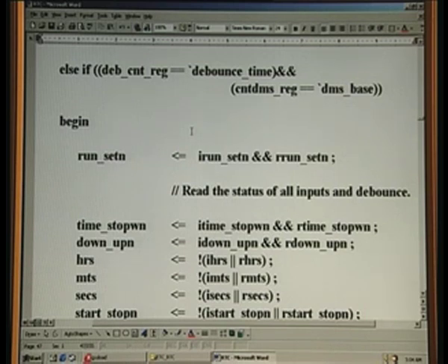It is this particular thing which gives that intelligence which reckons the pushing of the button. So this can be very easily done. Suppose this one is the present value of this push button, and R run was the previous value we have just now seen in the previous else condition, and that is nothing other than the same condition, but in the previous clock and when 0.1 second or whatever time base that matches has been met.